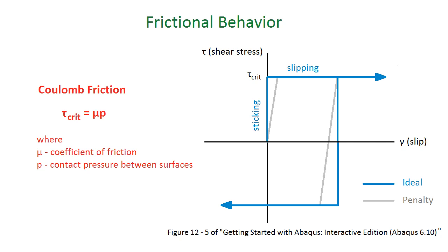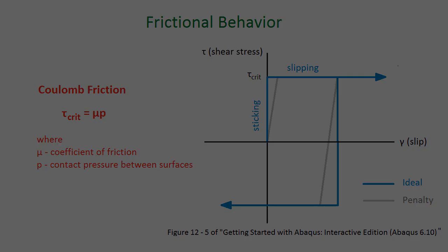With this formulation, there will be no slip between the surfaces till the shear stress has crossed the critical shear stress. The rough formulation specifies an infinite coefficient of friction, meaning that there is no slipping between the surfaces no matter how high the shear stress. And user-defined allows you to specify the shear interaction with user subroutines.